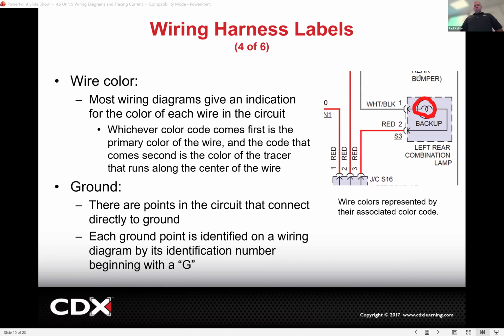We'll get into that when we do the car, but there'd be a connector. I can draw something. It'll be a little ugly, but there'll be this plastic connector with the 1 and the 2. You'd use a little back probe terminal and slip a back probe right in there, just barely touching the terminal. And boom, there's your test point. So don't worry, we're going to do that. That's a little separate. That's back probing.